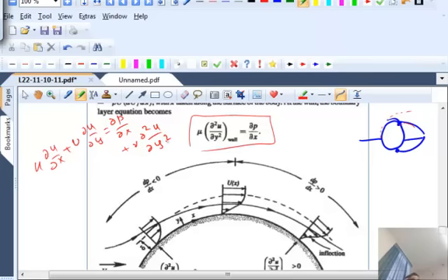That is the general Prandtl boundary layer equation. But on this curved wall, setting up a local coordinate system, watch here, x and y are perpendicular to each other, but x is always going along the length of the curve. X is measured along the length of the curve. So on that wall, u and v will be 0. No slip, impenetrability. So what you're left with is dp/dx equals mu times d squared u/dy squared.